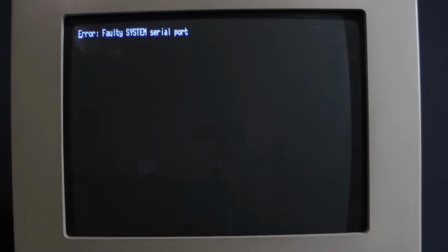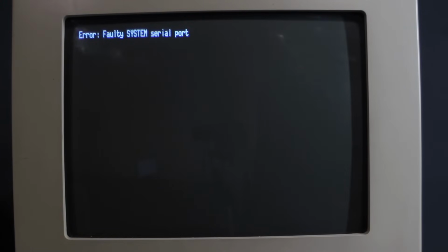This is not quite the error message I was expecting, but it is good news. So I turned off the manual DRAM refresh that I was doing and turned off the system DRAM refresh just to make sure that that really does go off. And when I exit the program to DOS, it rebooted and displayed this. I was expecting a parity error rather than this, but I'll take it. So it does really look like the DRAM refresh is going off and my code is working as expected. So that's one issue that we definitely have completely solved.